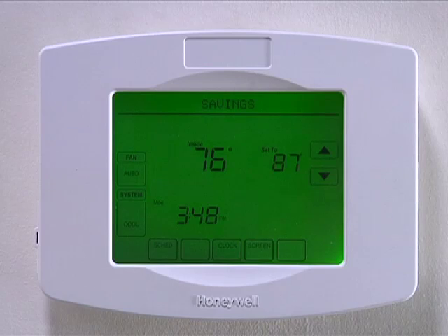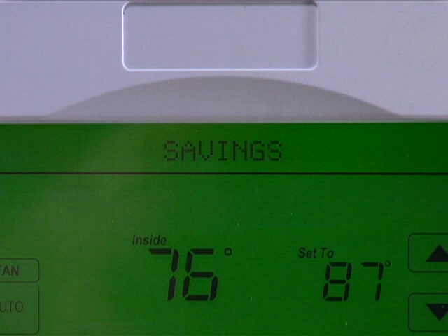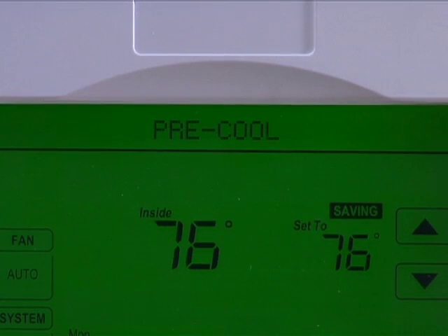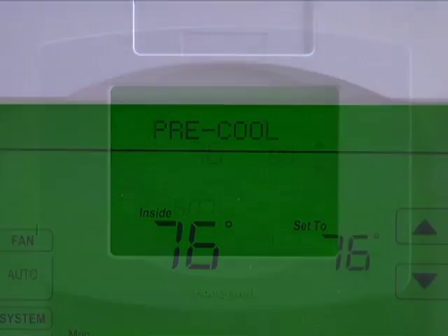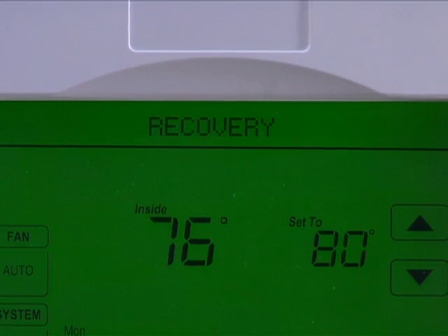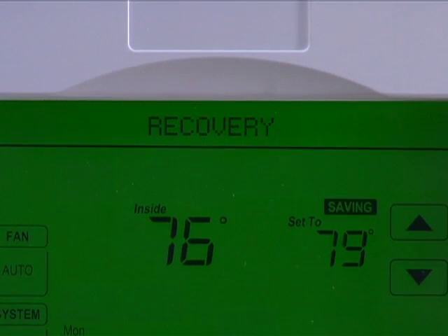Savings will appear when their smart thermostat is receiving a signal to perform a demand response load control event. Pre-cool will appear during the period immediately before a demand response control event if a pre-cool option is in use. Recovery will appear after a demand response load control event while the air conditioner is returning the indoor temperature to